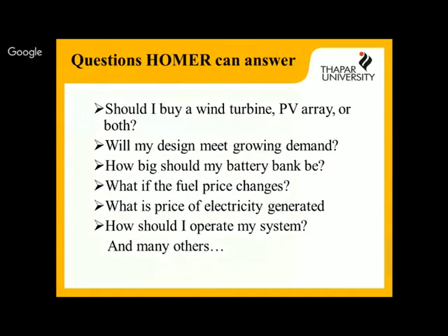And there will be some time when, let's say, you have a lesser load and your battery is full and you have plenty of energy with you. Then what are you going to do with that energy, right? In that case we can have a deferrable load also. Let's say I want to pump water from the ground, and it is not required at a particular time. Whenever I have access to electricity, I use it. Suppose I want to use it as heat energy or thermal energy, whatever. If you have enough, we can use it. If you don't have enough, we cannot use it. So a deferrable load will also be there in this system.